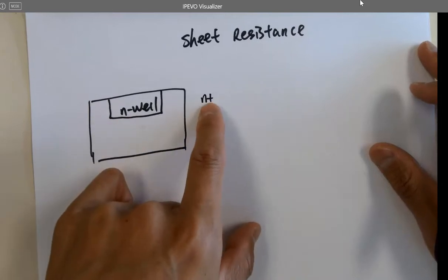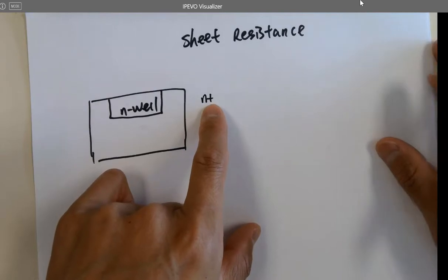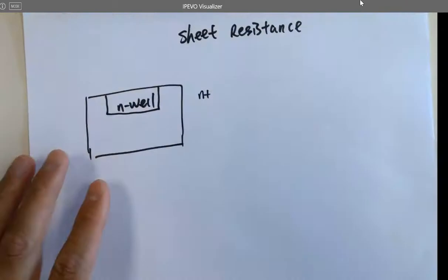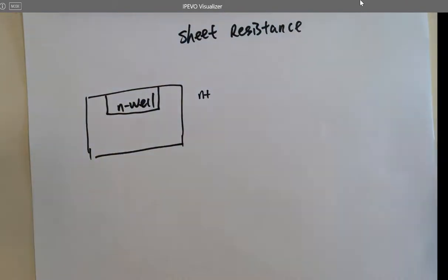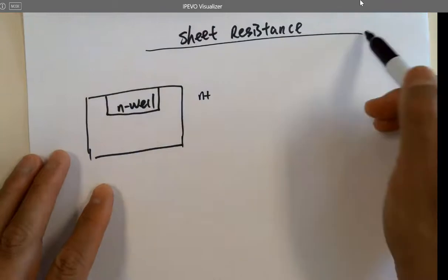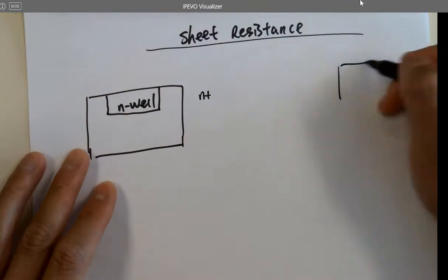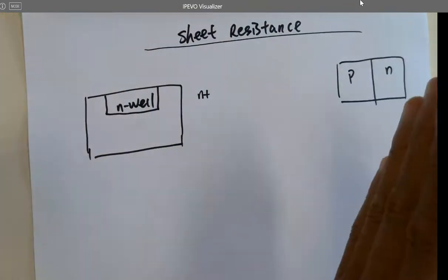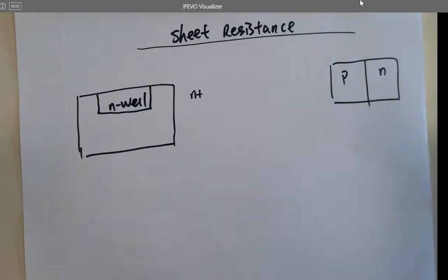These are being used as the drains and sources for the NMOSes, PMOSes. So N plus is going to be NMOS. You ask a really good question, why you need N and P, right? Today I'm going to introduce that later. Just form a diode. You have a P here, and here you put them together. It's a PN junction, a piece of P material and N material put together. That's a diode.